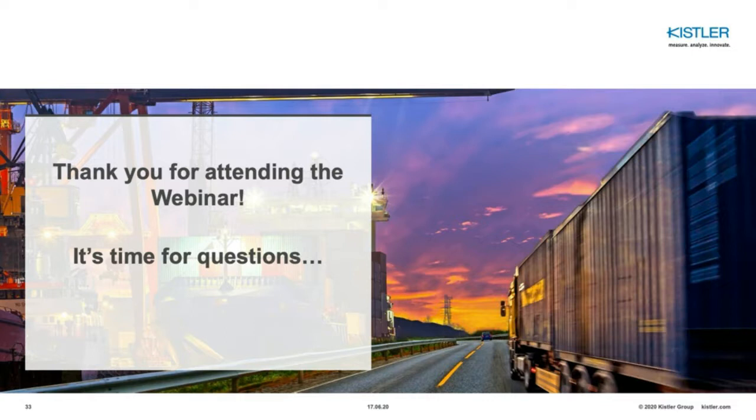And here then at the end it comes to the point on how far we want to further optimize the WIM system. As you've seen on the graphics about our measurement campaign, where we had all the average weights very close, optimized to 0%, this requires some specific calibrations, for example for specific vehicle types, or if we see some behavior at a particular site where the road maybe was not perfectly ideal and is behaving a little bit different depending on the driving position. Also truck runs with different driving positions can be done to calibrate the system.